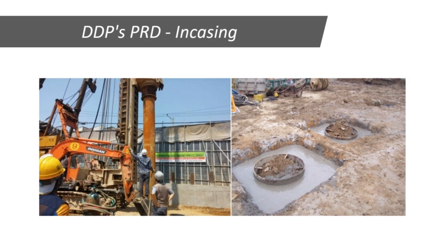The next step is production and installation of encasing. In the encasing production, we use the required thickness to prevent deformation of the cross-section due to earth pressure, and we use a frame to achieve verticality when welding, and then we flatten the upper part and insert the angle.